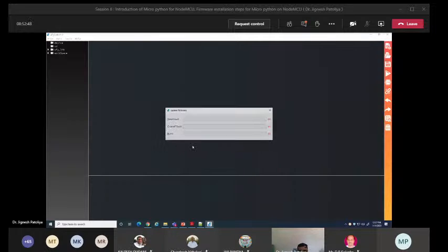Click OK. Then 3 windows: download, erase flash and burn. Right now it has downloaded this binary file. Right now it is erasing my previous flash memory, and this process shows that this binary file goes inside this chip. And if you look at my NodeMCU, this is my hand, one upper LED is blinking. What is that?